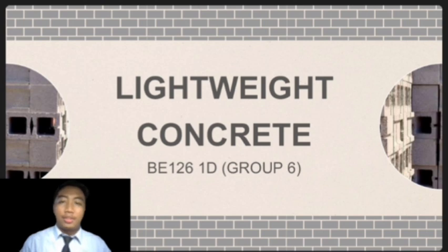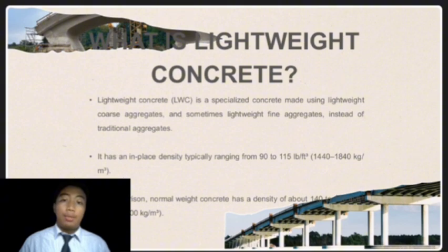My name is Ahmad Fauzan Aziman bin Ahmad Zaihuri, and today I will be talking about an overview of lightweight concrete, a specialized material that plays a crucial role in modern construction. So what exactly is lightweight concrete? As the name suggests, it is a specialized concrete that is made differently than traditional mixes. Instead of dense stone and sand, it utilizes lightweight coarse aggregates and sometimes lightweight fine aggregates.